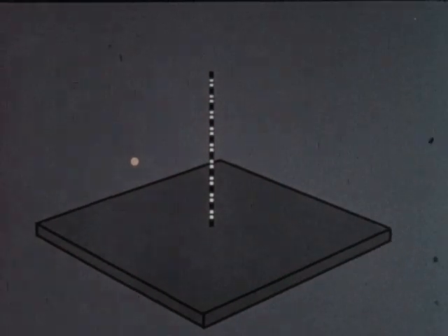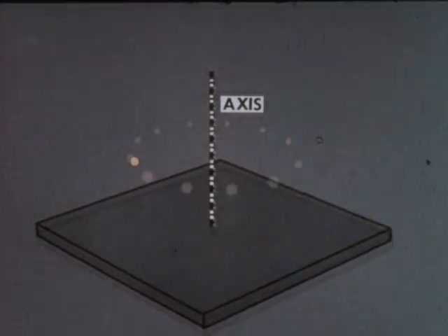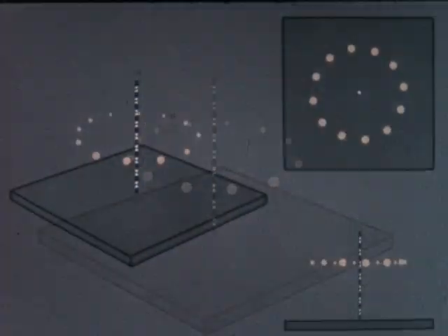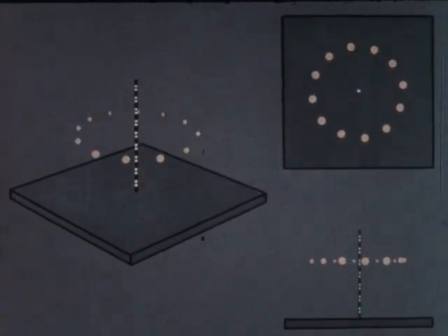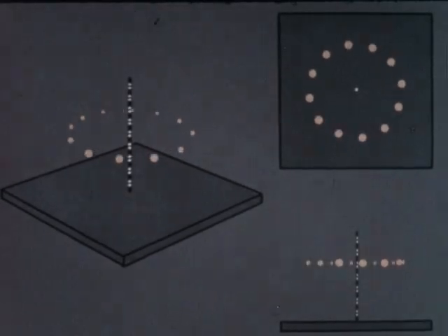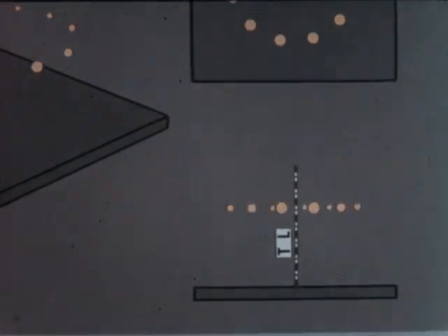The rotation of a point about an axis is basic to all problems of revolution. When the axis of revolution appears as a point, the path of revolution shows as a circle. Where the axis appears in true length, the path of revolution shows as a line.